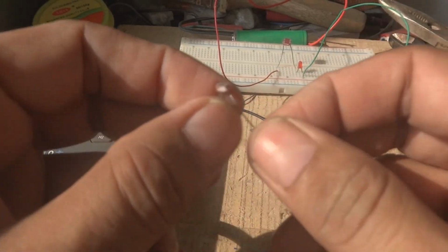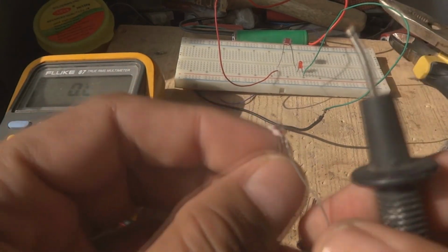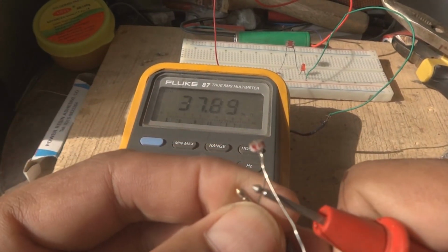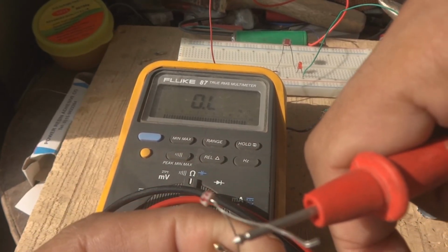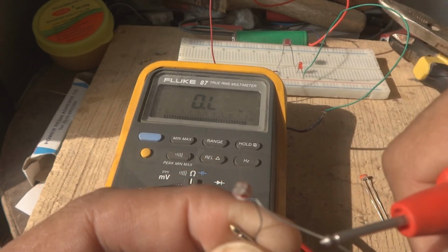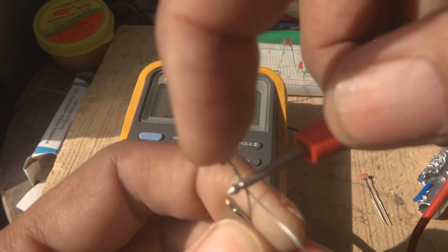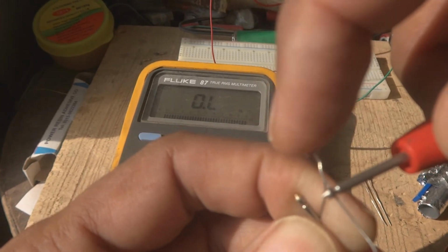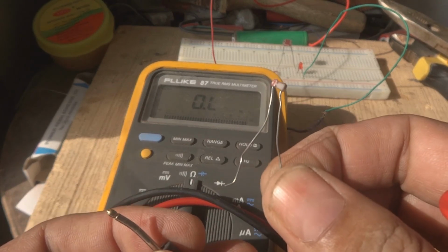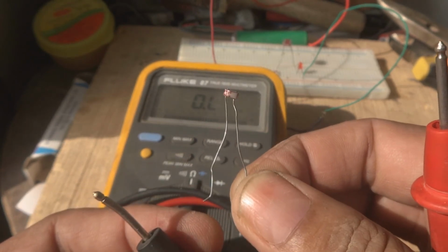Now I will show you something else about the LDR. This is a fact that if you are going to purchase LDRs in the market, nowadays they are coming defective. You can see this LDR, a new one I just purchased, is not giving any resistance value on the meter, in the day or in the night. It only shows OL, out of limits. So it means that this LDR is defective. This is an open circuit. Unfortunately, these LDRs are sold in the market. If you purchase an LDR like this, you will not be able to continue your experiment. So take care and don't purchase such LDRs from the market.